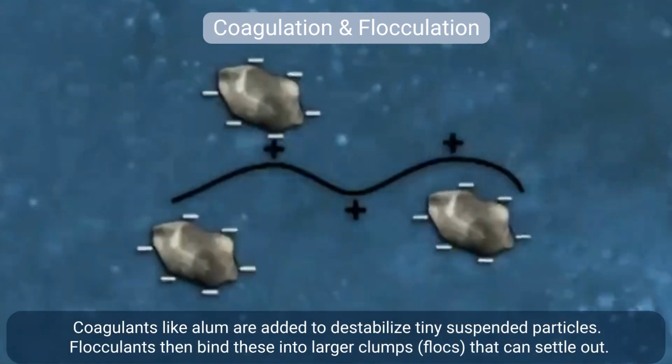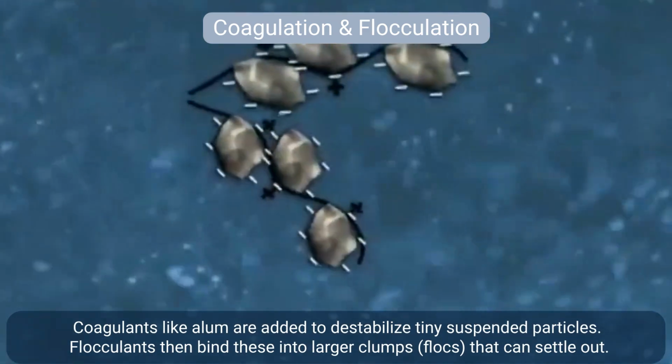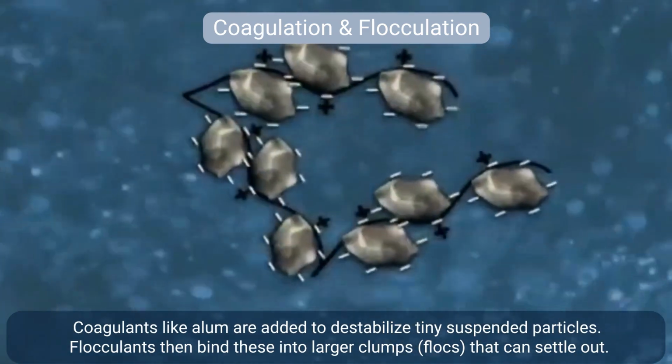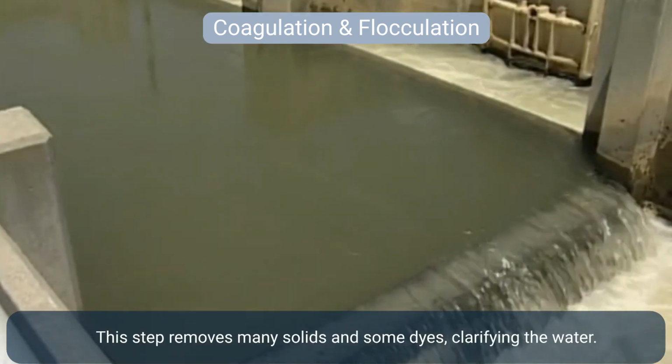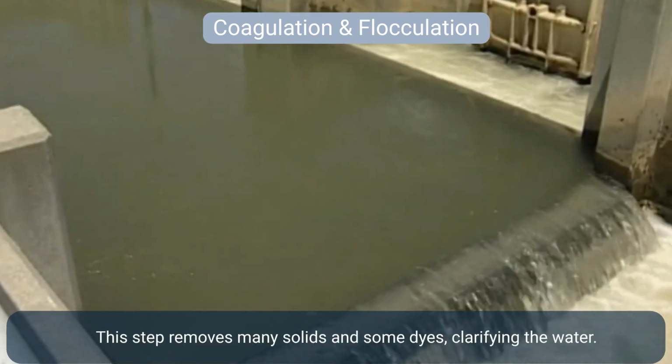Coagulants like alum are added to destabilize tiny suspended particles. Flocculants then bind these into larger clumps, flocs, that can settle out. This step removes many solids and some dyes, clarifying the water.